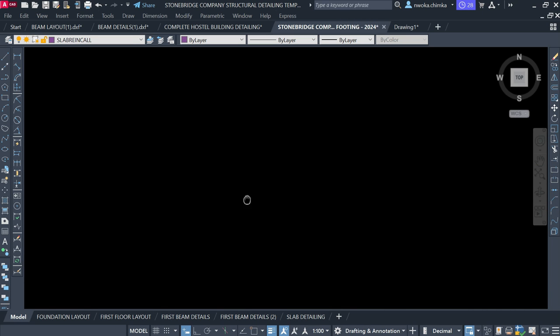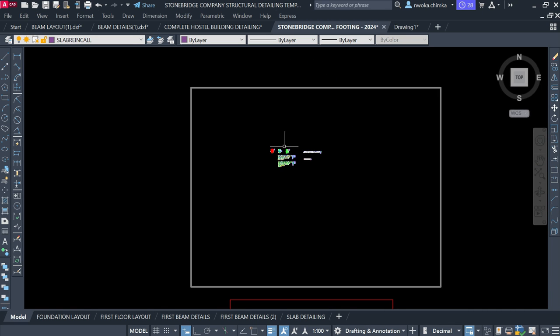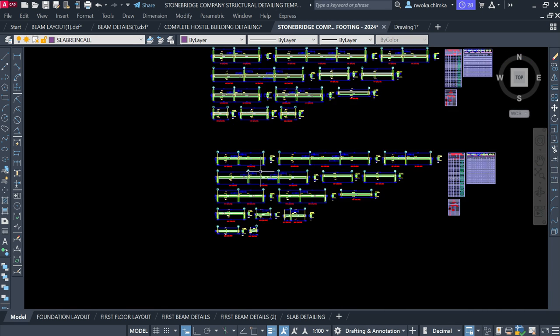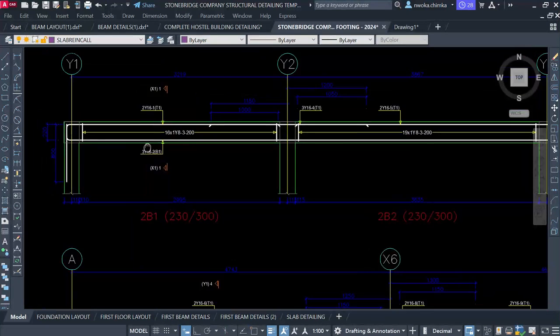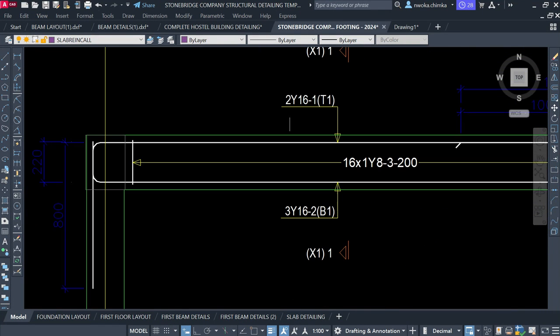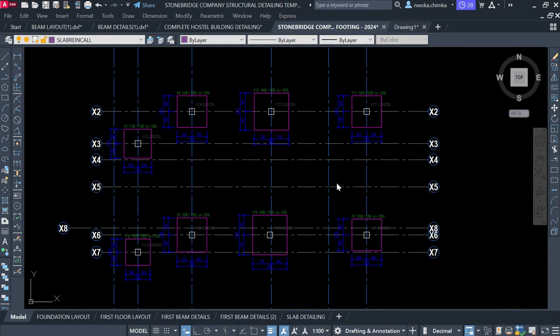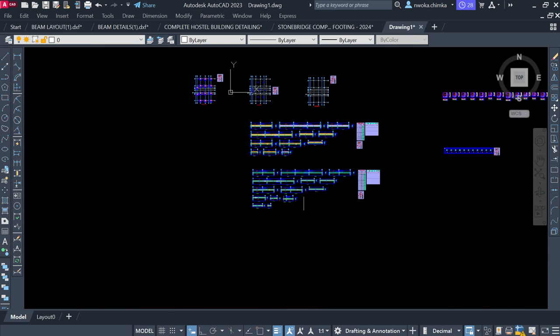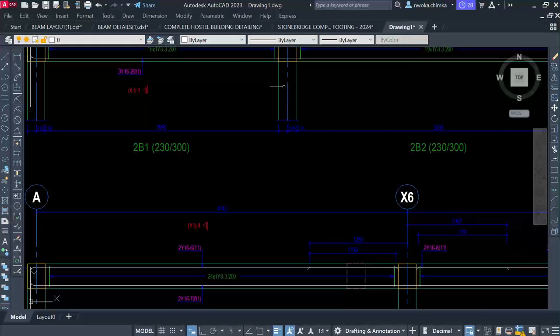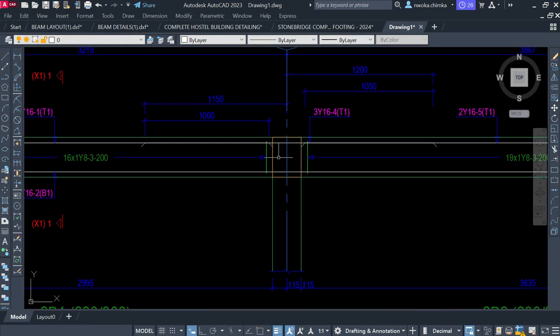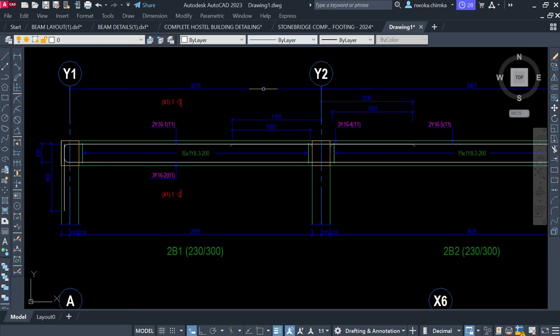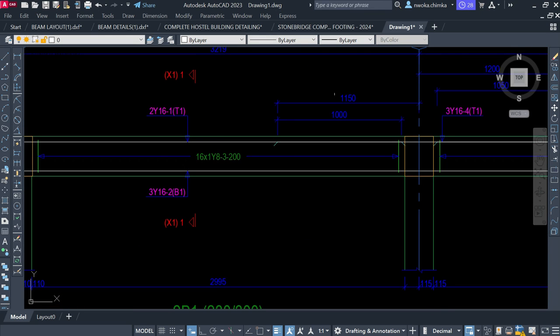So this is just the first step, which is pasting first. Only pasting alone can help you optimize your drawing a bit. As you can see, this is now your beam details for the roof, and this is your beam details that came from Prota Structure. The whole idea is that the STONEBRIDGE template gives you a standard method of drawing, compared to what was here before.